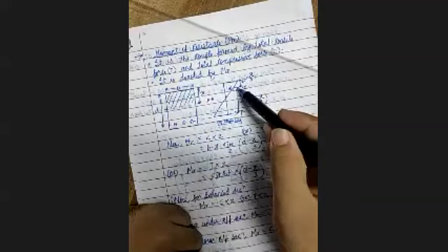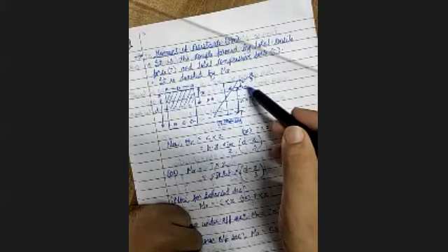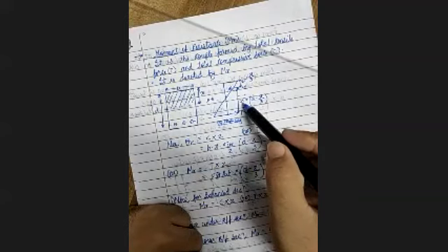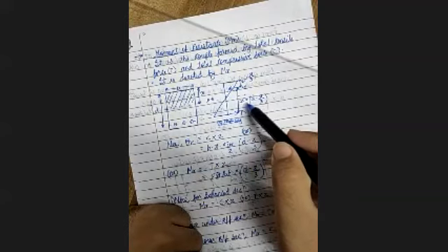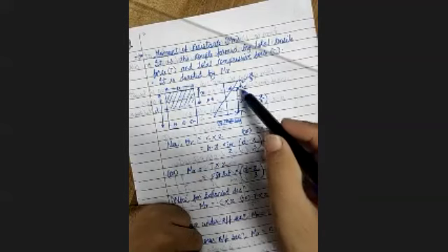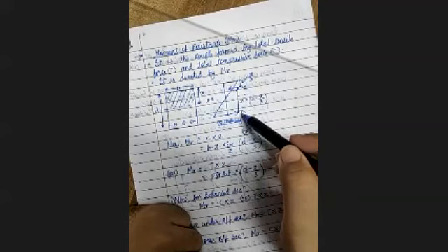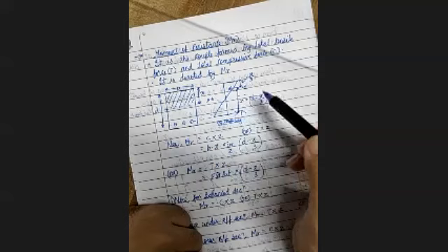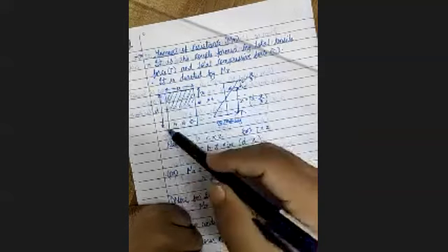Now the distance between these two forces, that is your compressive force C and the total tensile force T, is called the lever arm, which is denoted by Z. Can you see on the sheet that Z is the distance between the total compressive force C and total tensile force T. We know that D is the distance from the top compression fiber to the center of the reinforcement, and this other distance is x by 3.